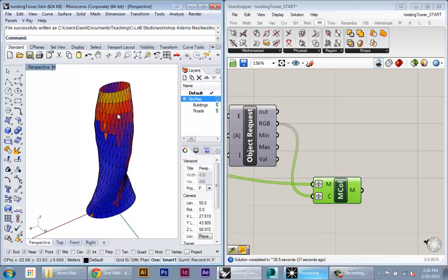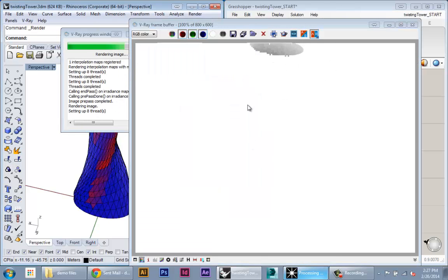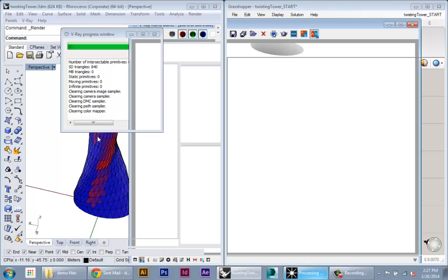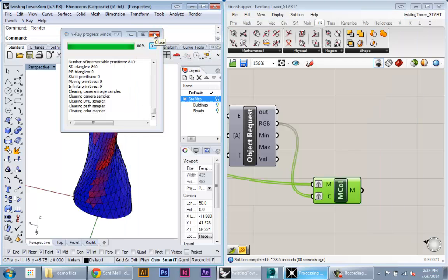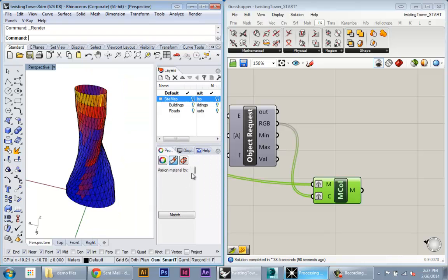The other kind of color that's in Rhino is the material color. And this is a completely different property, and it completely relates to what happens during render time. If you hit render, the colors actually won't show up. So here I'm rendering, everything is white. Because even though the mesh has color properties in Rhino, it doesn't have any material. So if we click on one of these meshes and we go to the material assignment, see it's assigned by layer, and the layer that we're on doesn't have any material assignments, so it's never going to render those colors.